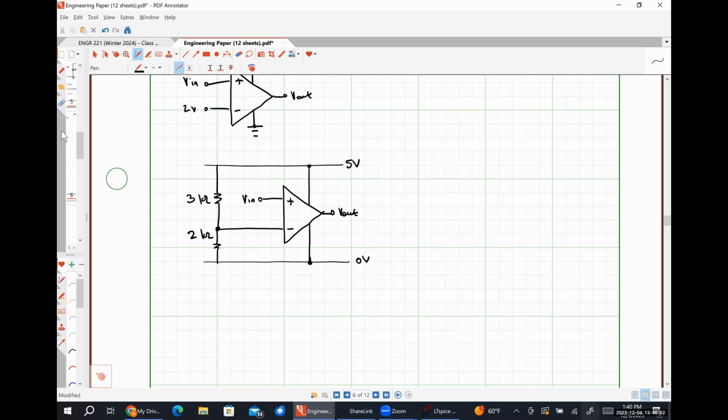All right. So the answer is for which part? For problem one, it's just graphing. So the peak value of the input voltage is 1.5 volts, because that says 1.5 and that's the maximum. I'm looking at it because I'm trying to figure out whether or not saturation distortion will be a thing. If it's below the peak value, that's less likely to cause saturation. Same thing for the negative. Yeah, exactly right. So my voltage gain is defined to be 12.